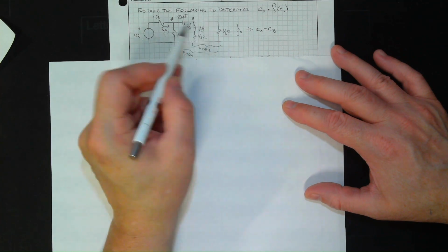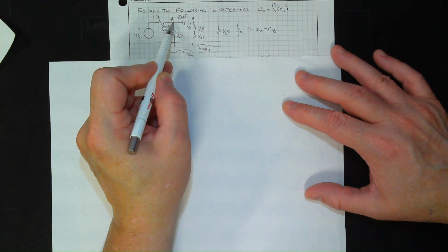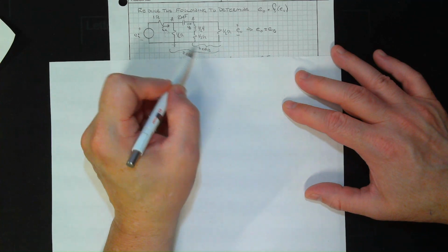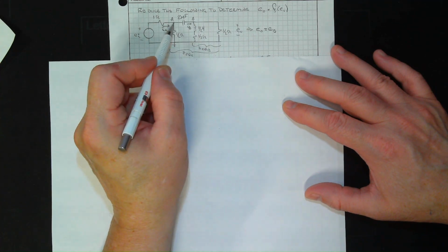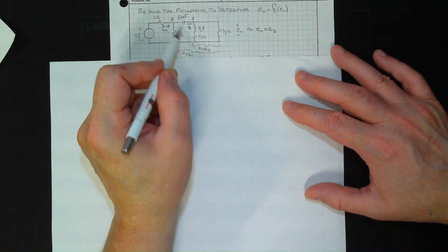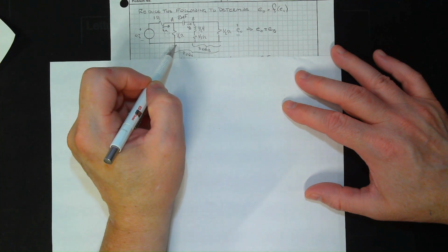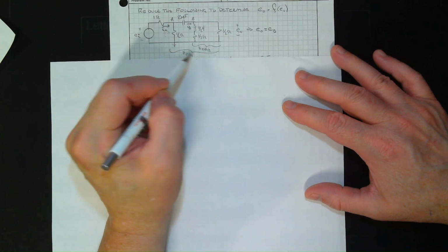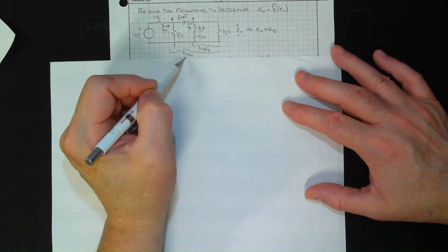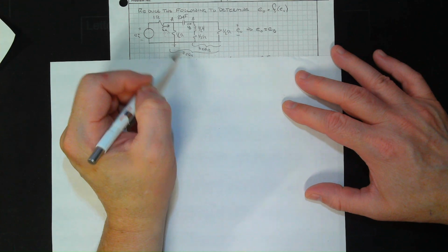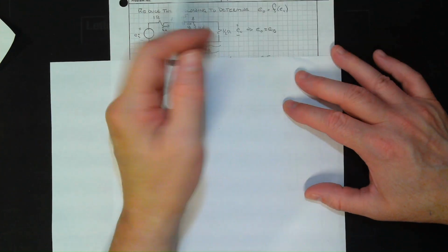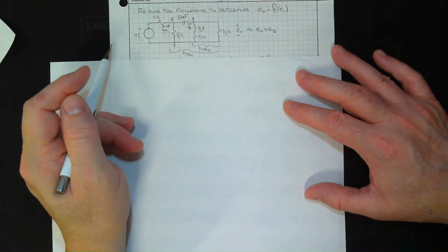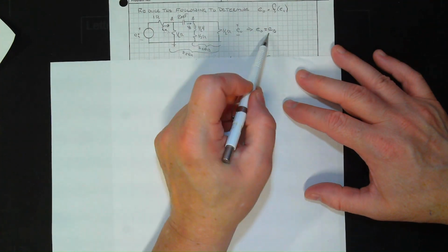Now, once I get this, we'll see that relative to the voltage of EA, these two and then this big thing, they're all in series. So the voltage from here through all of this mess is equal to the voltage across this half ohm resistor. And we'll call all of this piece here ZEQA, so the equivalent impedance from there back. ZEQB is the impedance from there back. All right, so we've made one observation.